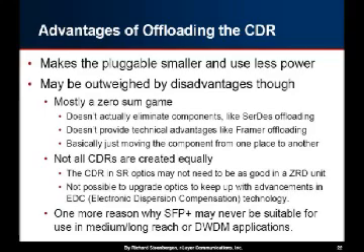Whereas if that's been moved to the board, you're going to be very limited in what kind of reaches you can get. And also there's a lot of advancements in things like electronic dispersion compensation technology, where you might be able to end up removing the 50 kilometer spool of fiber that you have to use to undisperse all of the wavelengths. You get the slope back. So you're cutting yourself short if you've offloaded all of these components onto your board, because now you've got to upgrade this entire board.